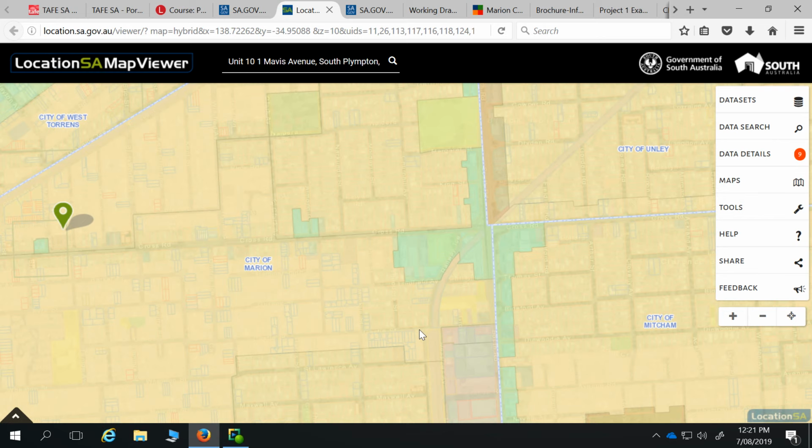Then we're going to set up the wall type, aren't we? So what's the wall type? What was the external walls? The weatherboard. So it's a 90 stud with a weatherboard. How thick are we going to allow for the weatherboard? Straight, if it goes straight onto the frame. So that's the next bit of research. The answer is not just going to come to you because you probably haven't used that product before.